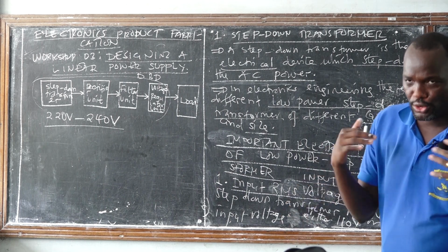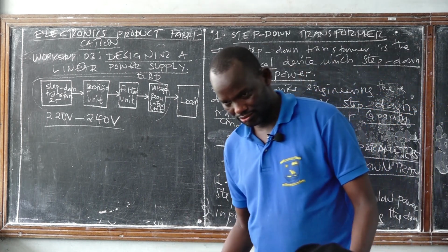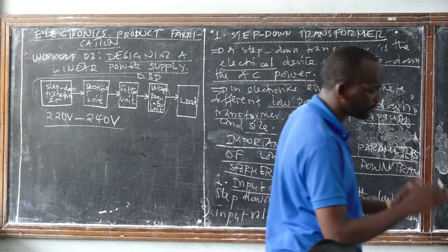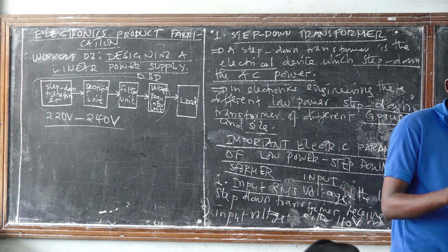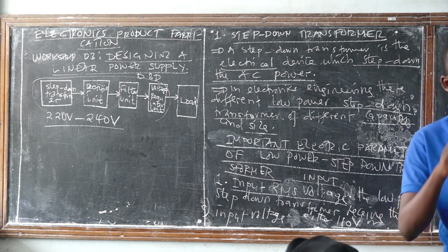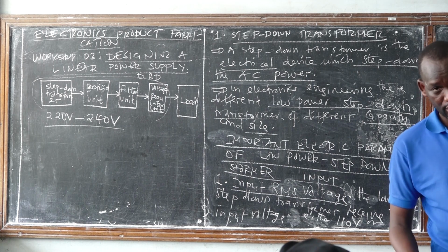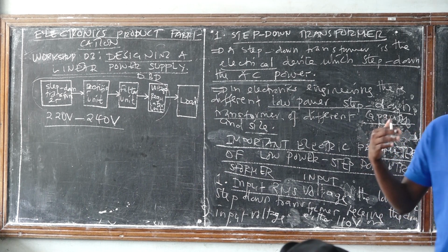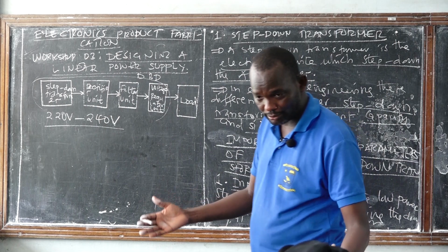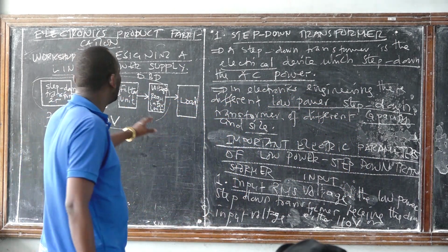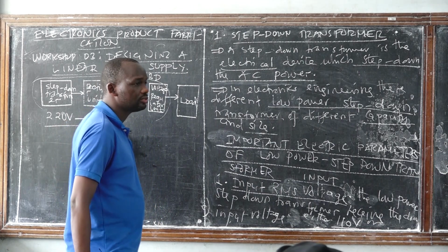In the workshop we'll measure; it usually ranges from 227 to 230 volt. But I don't want to tell you a lot. You will measure it yourself and know the domestic voltage by that time, because it varies sometimes, but it cannot vary outside of this range.